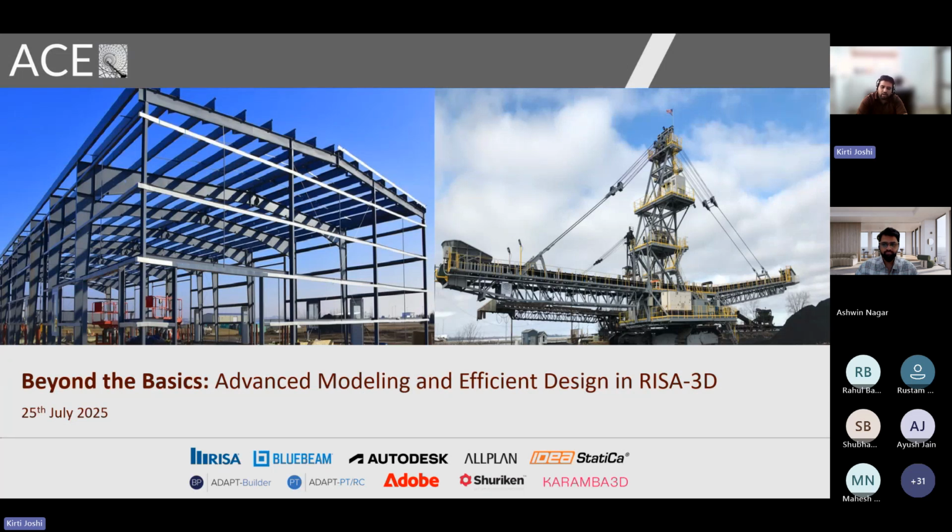The visual on the slide reflects a great use case of RISA-3D. On the right side are the modular steel pipe racks for the Freeport LPG terminal in the US that were prefabricated off site and transported to the construction site by ship. Each unit was designed in RISA-3D to withstand the gravity, the hurricane wind, and the motion loads that arise during the transport at sea.